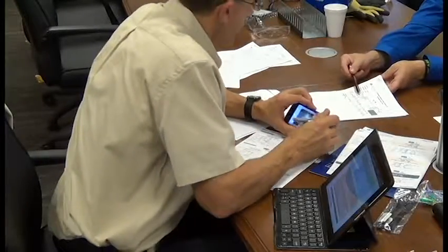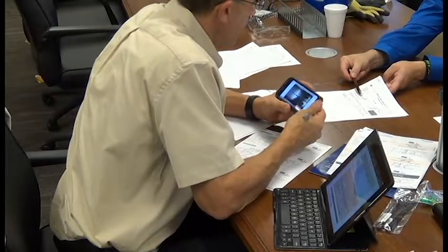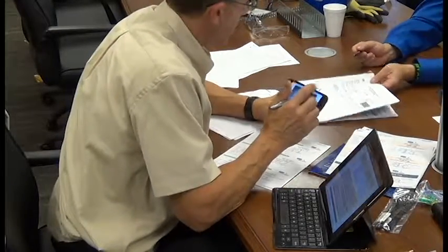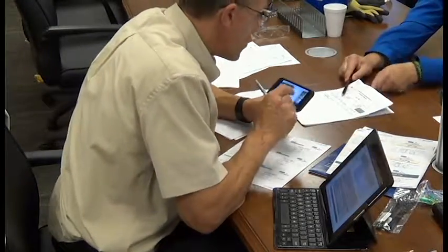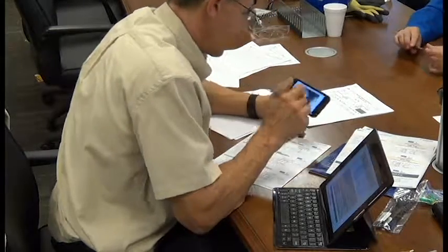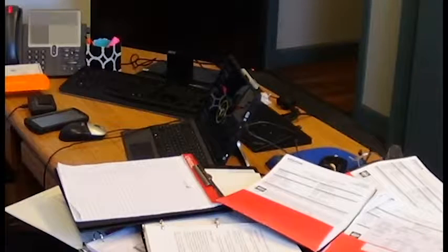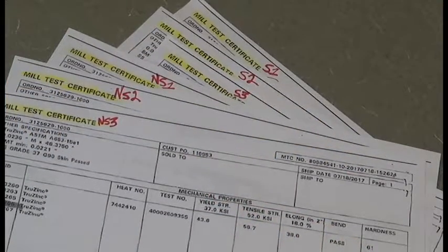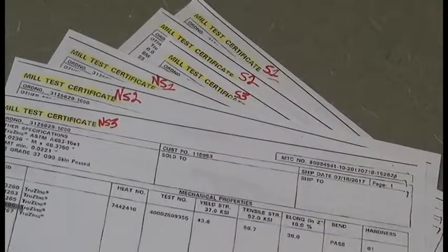The cornerstone of adequate traceability is the documentation containing key information about the material being used. This documentation may take the form of a PO, a mill cert, or an independent third-party test certificate. Bills of lading and shipping records are not mill certifications and do not contain the information required for this traceability. The key document, as required by the industry standards, must contain the following: